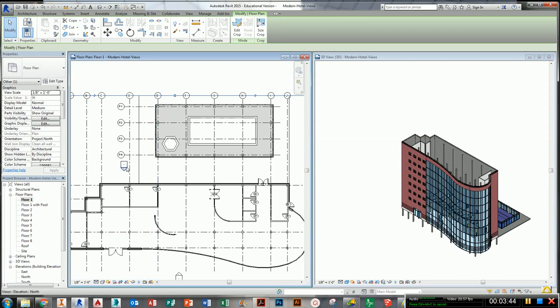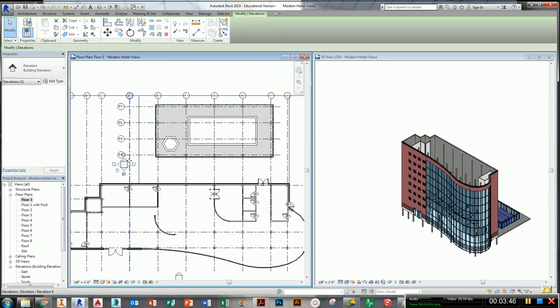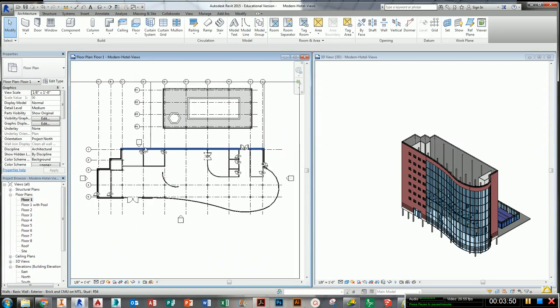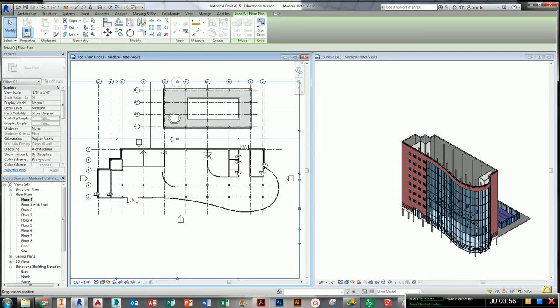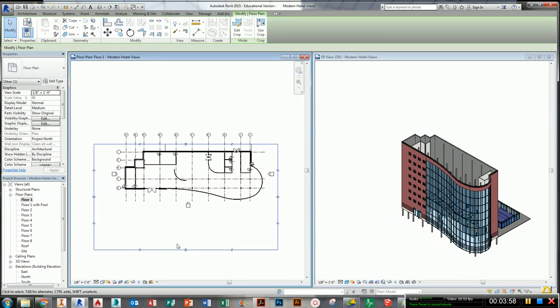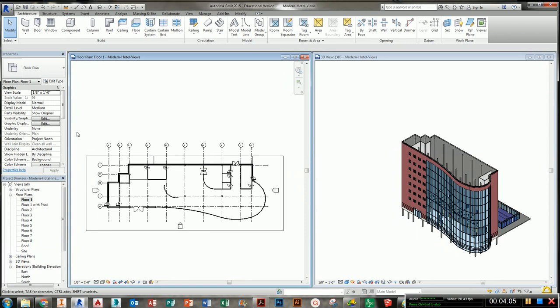So let's grab, and you'll see later what the difference between clicking on the arrow gives you a line, and clicking on the box gives you a checkbox. So let's pull this back like we should. So we want to make this look exactly like the books. Alright, now we've got a clean cropped building, and we're going to hide crop region because now we've shown as much of that view as we'd really like to.